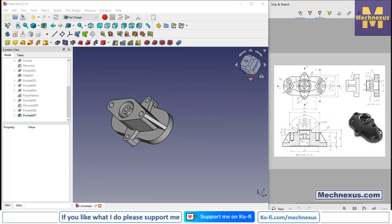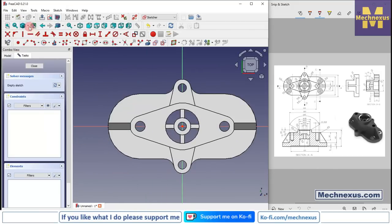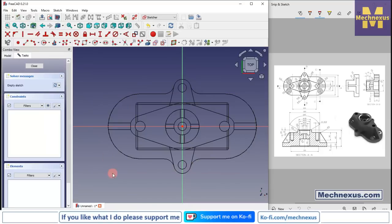And now we will create these 4 holes of a counter bore. So press 0 and select this face and click on the sketch, and from here we will switch to the wireframe, and we will create two circles, and we will use the symmetricity.